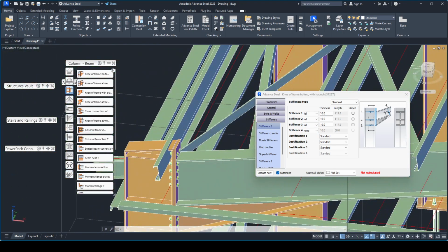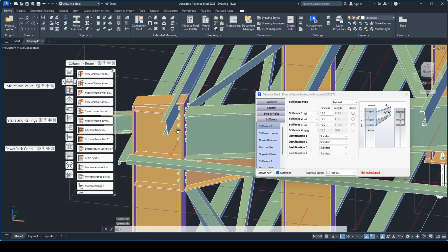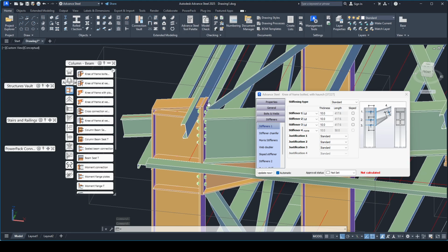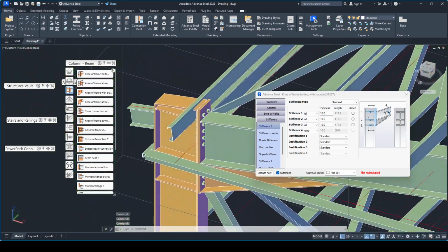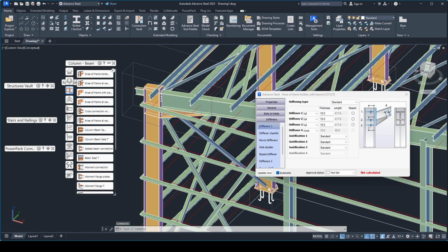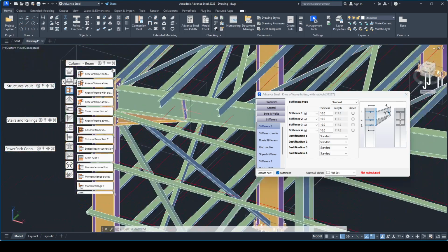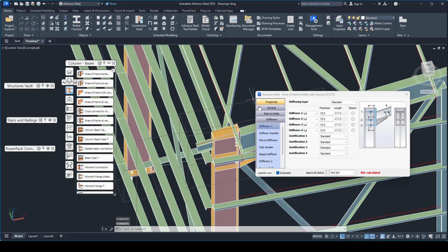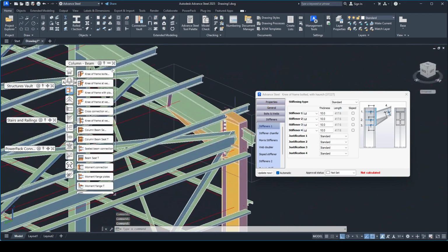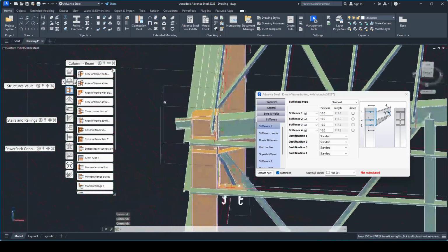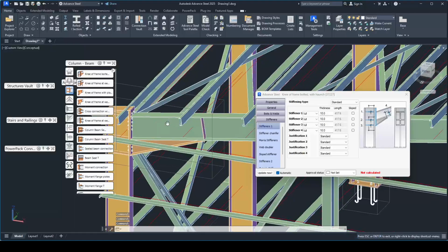Okay, and you can check and update with the design connection. I just input here full. You can optimize the steel connection and the plate thickness 10. And for the stiffener 4, we also use full. You see here at the end of hole, the stiffener we use in both directions or both sides. Okay, correct. Now we complete for this connection.